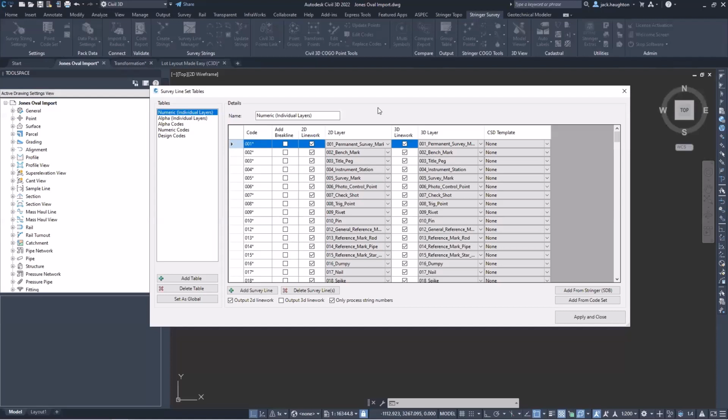This way, whenever you start a new drawing, you simply open that DWT, save it as the drawing you wish to be, and then you have all of your layer and your description key set information preloaded and ready to go.